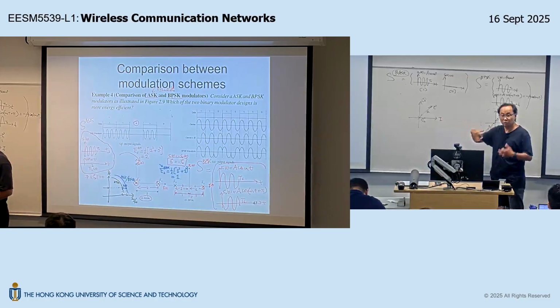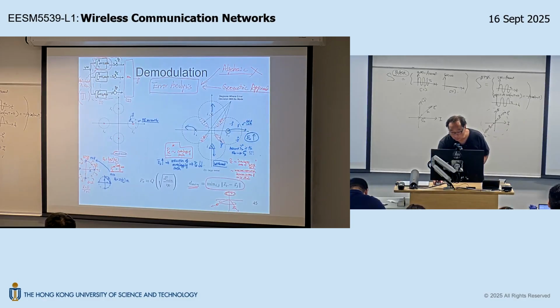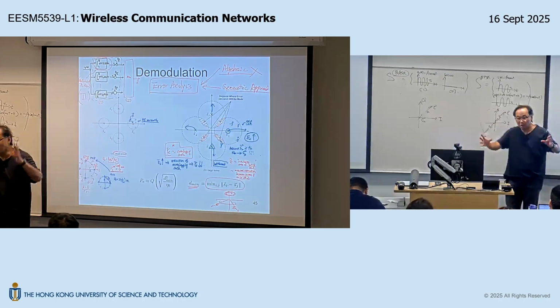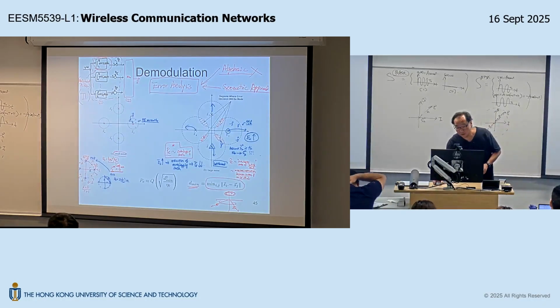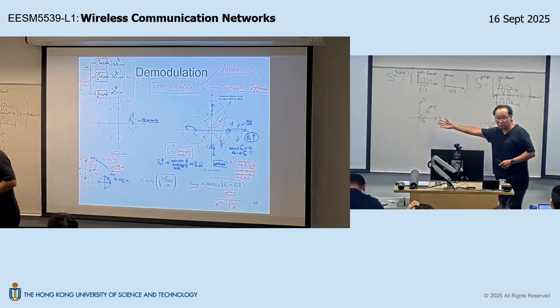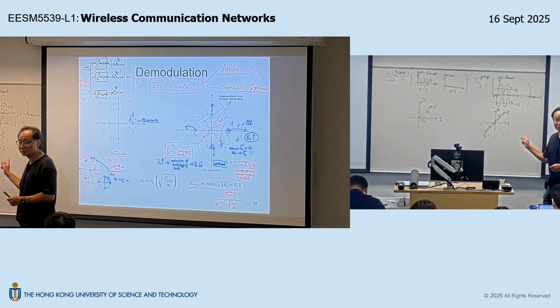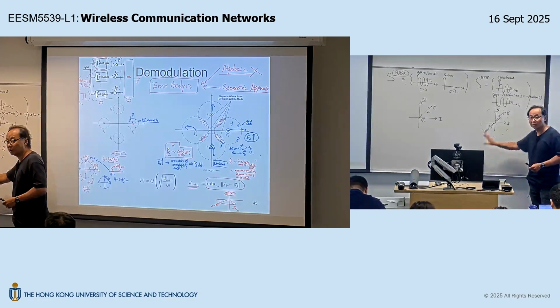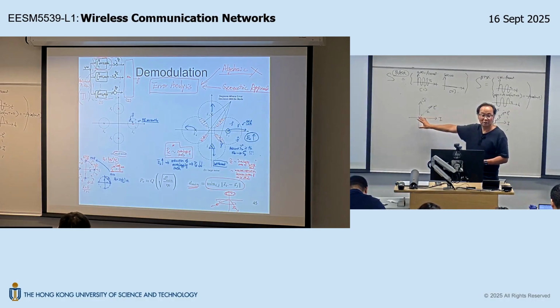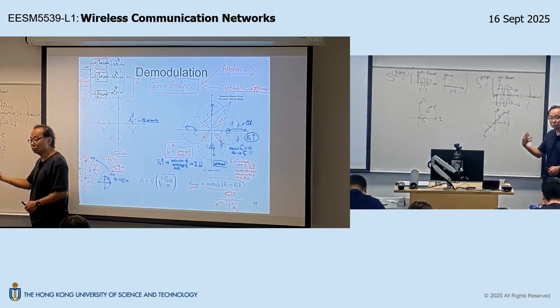Agree? Because once again, what is error probability? Error probability is determined by the overlapping area between the 2 noise clouds. The size of the noise cloud is determined by noise power, which we cannot change. So the remaining factor that affects the overlapping area is the separation of the centers of the noise clouds. By this setting, the separation of the centers of the 2 noise clouds is equalized to be 2 units in both cases. So therefore, they will have the same overlapping area, and therefore, they will have the same error probability. Agree? Okay. So now our remaining task is to figure out which one consumes more energy.